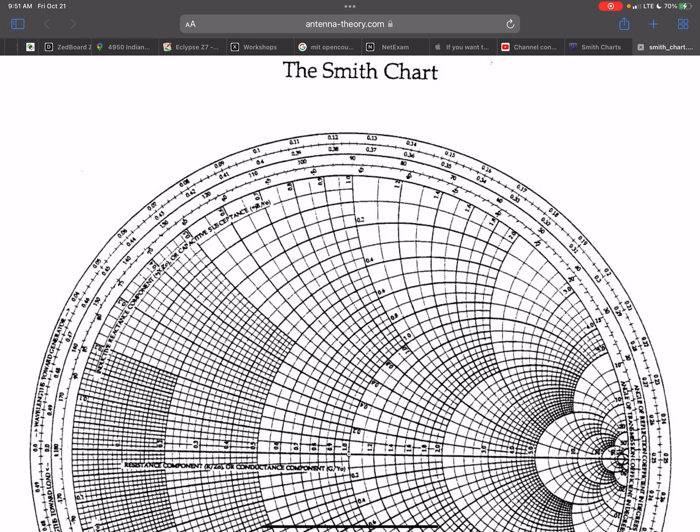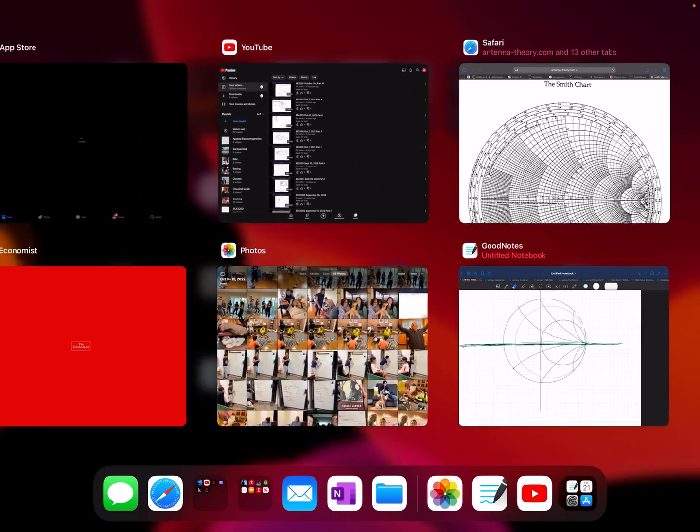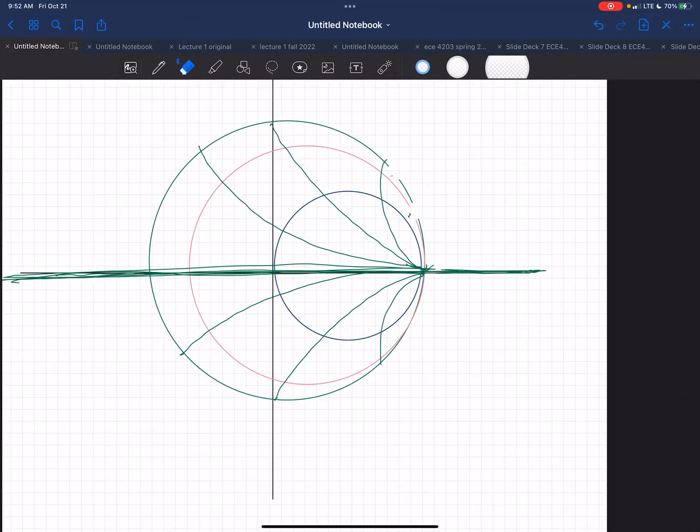You'd make a bunch of copies of that transmission line, and at different lengths away from the load, you would put a slot to stick a probe in to measure the voltage at that point. I'll get into that, but you have to find some way of doing these measurements, or you use the Smith chart. Sorry, I keep going on tangents, but let's just stick with this for now.